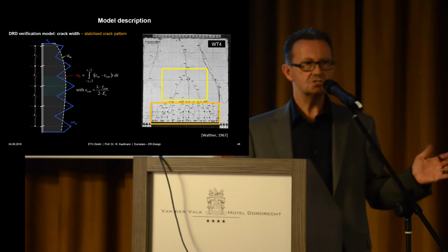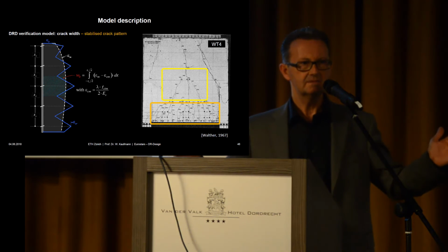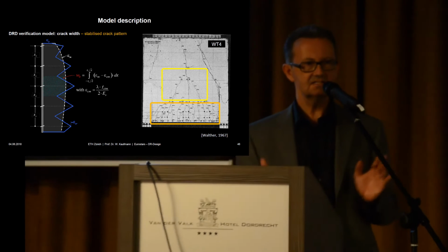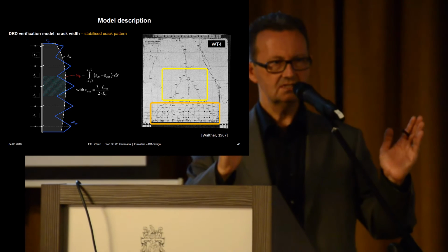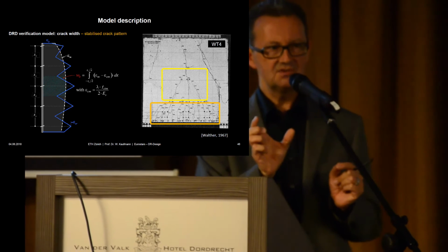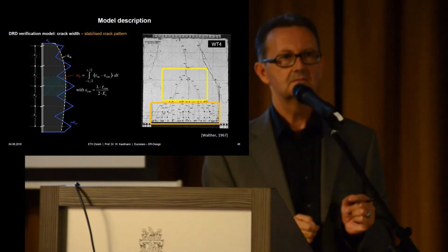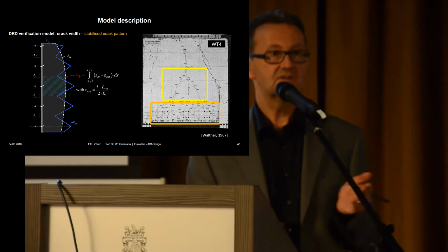If you take a tension cord, load it in tension, and make it crack, you can determine the crack spacing theoretically by no more exactness than a factor of 2. Because you may get the crack spacing, and then you have the tensile strength of the concrete just reached in between 2 cracks. And the new crack may form or not. That's a factor of 2.